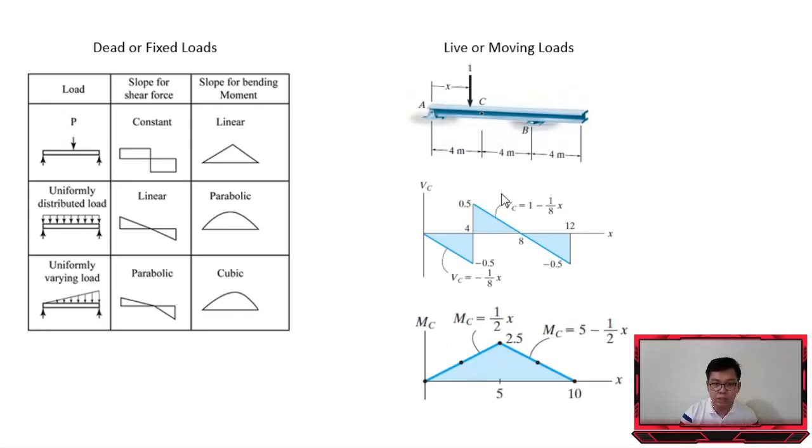Notice na sa diagrams natin dito, meron tayong dalawang axis. Tignan nyo, meron tayong x-axis. Now, the x-axis is actually similar lang sa natutunan natin sa shear and moment diagrams during strength of materials. Yung x-axis actually represents the length of the beam. So, simula ka dito sa 0. So, meaning, pag ito 4, this is actually andito sa C. Pag ito 8, this is actually andyan sa support at B. Meron tayong x-axis and same pa din, meron tayong y-axis din.